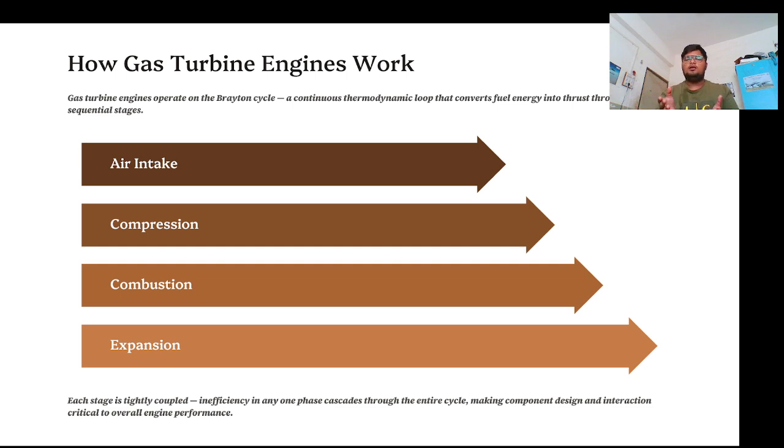The combustion chamber has the sole work of doing the propulsion. That is, it mixes the fuel with the air to make the air fuel ratio, and then that air fuel mixture is combusted by the ignition. Then those expanded gases pass through the turbine, which is the expansion stage. The turbine also has two stages, high pressure turbine and low pressure turbine. The high pressure turbine runs the high pressure compressor, and the low pressure turbine runs the low pressure compressor.